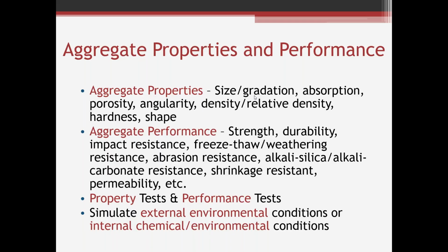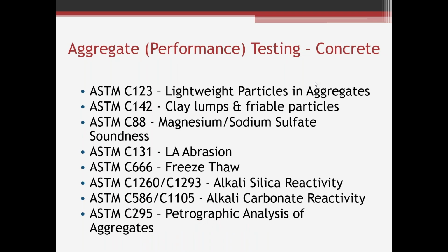We do tests on both aggregate properties and aggregate performance. Again, this presentation is going to be more geared towards performance tests rather than those property tests. In the performance tests, we're typically trying to simulate some sort of external environment or condition that the aggregate, or eventually the concrete, is going to be exposed to, whether it's freeze thaw or impact. Maybe it's an internal environment to the concrete where alkali silica reactivity might come into play. But again, we're trying to simulate some sort of environment that the aggregate's going to be exposed to.